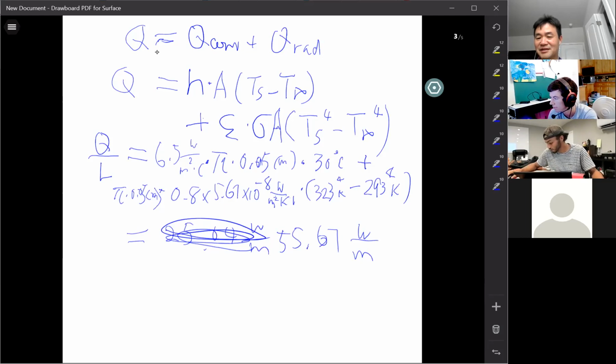So that's how you use the equation Q conduction equal to Q convection to figure out that T surface. Gotcha. That's why I said this is a difficult problem, because the conduction part of the calculation is a little tricky because it's cylindrical coordinate. Okay. Good.